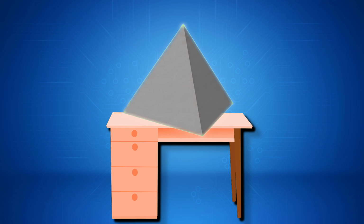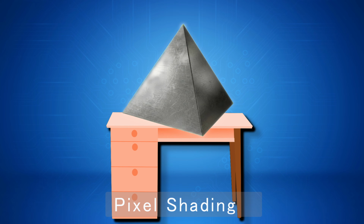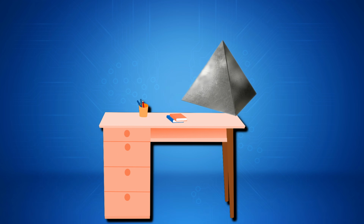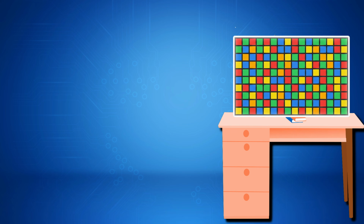It converts the vector shapes into a grid of pixel candidates. It's basically creating a 2D stencil for the final image. Then the third step is pixel shading. This is the most intensive part. For every single pixel in that stencil, the GPU runs a tiny program called a pixel shader to figure out its exact final color. This is where all the complex lighting, shadows, and textures are calculated. And then fourth, our output merger. Finally, the GPU takes that final colored pixel and writes it into the frame buffer in VRAM. And boom, in just a few milliseconds, the GPU has done this for all 8 million pixels, and we now have one complete 2D frame sitting in the VRAM workbench, ready to be seen.